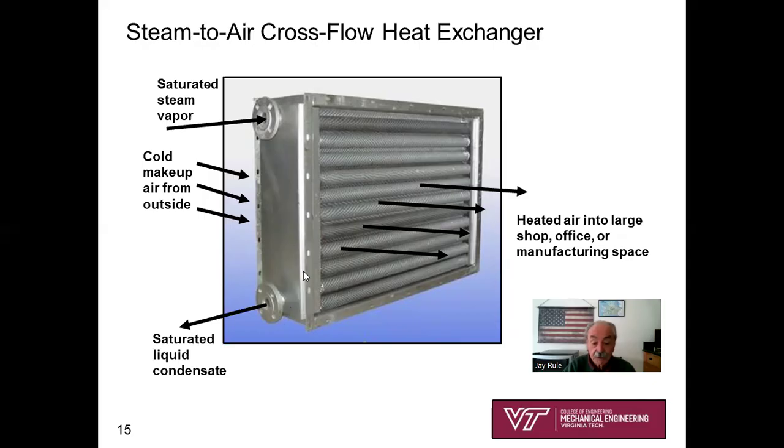And this steam is condensing and being returned back to a condensate handling location. This is not considered a condenser. It's called a steam air heater, even though the steam turns out to be condensing.